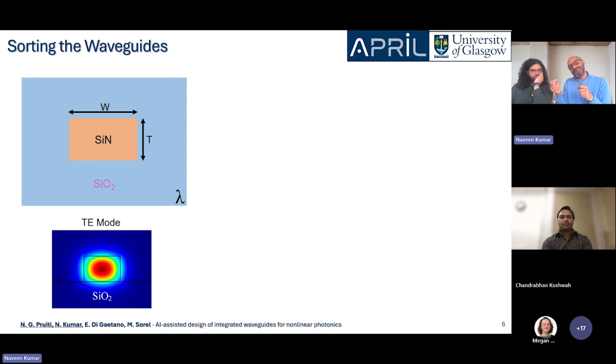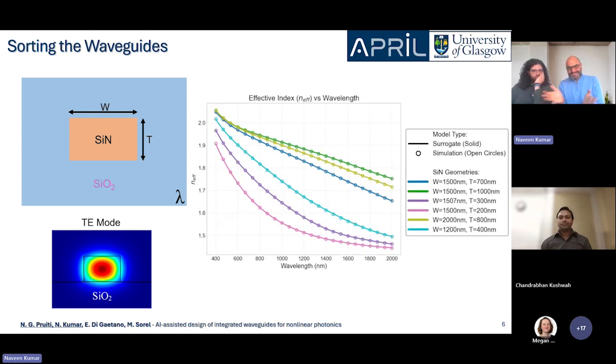And for every single mode, those extracted values are different. So those become multimodal waveguides. So for the fundamental mode, if I take these values with variability and I make a surrogate model with a simple MLP, matching these is quite easy because they are not complex.